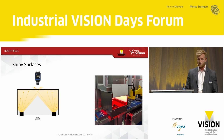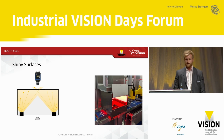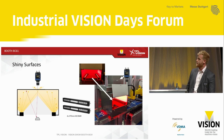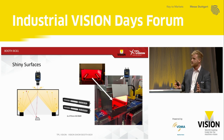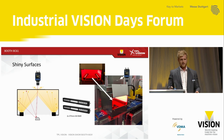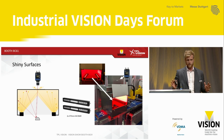Now, it gets even more challenging when you start adding curved surfaces. So shiny surfaces are always a problem in machine vision, but when you imagine that your camera is looking at the light in the reflection, you want to make sure that the top surface of whatever you're inspecting is filled with light, or that whatever's in the reflection of the part you're inspecting is an illuminated area, and it's illuminated really uniformly.